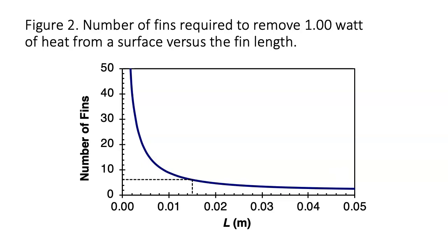Note that using fins with a length of around 10 millimeters would work well for this case because the number needed has already decreased significantly, but you have not reached the point where adding more length has minimal impact on the total number needed.